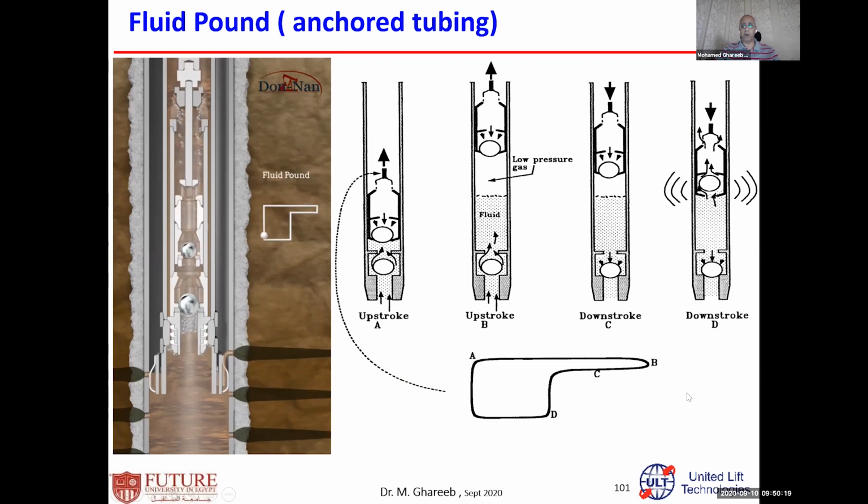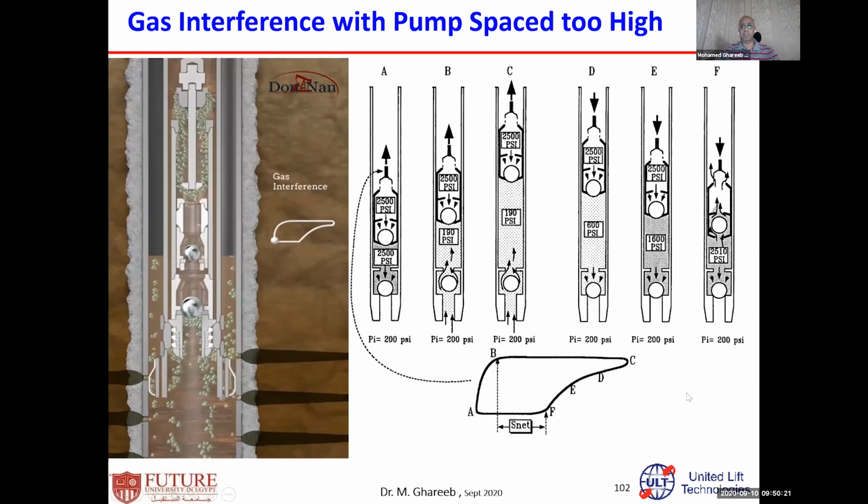What else can I find in that gas? How the gas affects downhole pumps and downhole cards, how it looks, and how from downhole cards I can say, yes, there is gas; no, there is fluid pounding; no, there is some gas. How does the gas affect it, and how does the pump run on the gas, and so on.